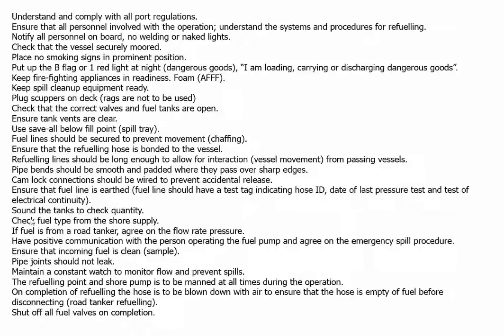Sound the tanks, check quantity, check fuel type from supply. If it's from a road tanker, agree on flow rate and pressure. Positive communication with the person operating the fuel pump. Ensure the incoming fuel is clean. Pipe joints shouldn't leak, maintain a constant watch, refueling points to be manned. On completion of refueling, hoses to be blown through with air, and shut off all valves.